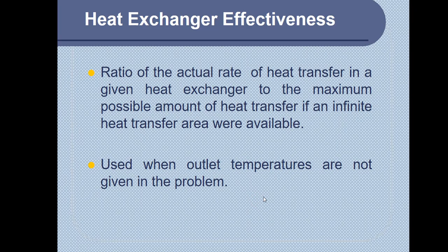Okay, now, what about if your temperatures are not complete and there is no way that you can complete them? An example is when you're only given two inlet temperatures and you're not given the outlet temperatures of your fluids. You cannot use the LMTD method or the log mean temperature difference method. There is another method that you can use, and that particular method is the heat exchanger effectiveness.